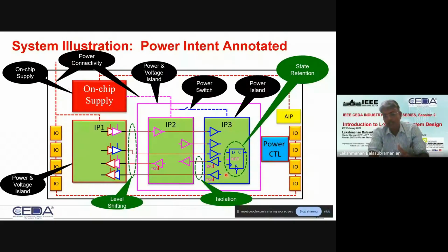Normally this IP3, when it operates, only has dynamic power, and of course leakage power. When you have a permanently connected resistor, for when IP3 is off, all of these resistors are going to consume dynamic power and static power whenever logic 1 is driven as output of IP3. That's going to increase your dynamic power heavily.